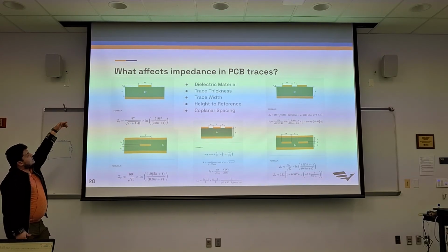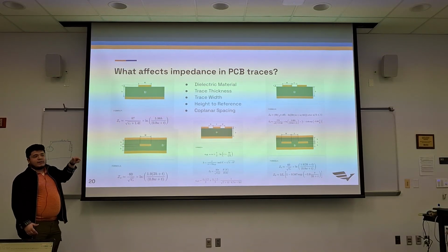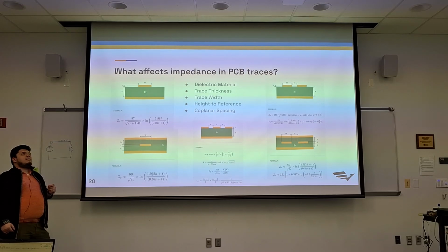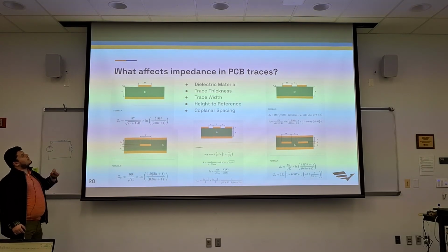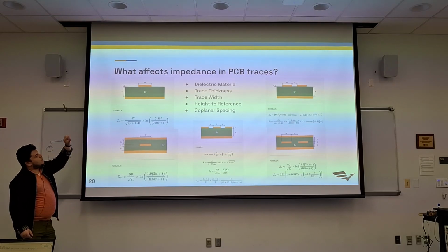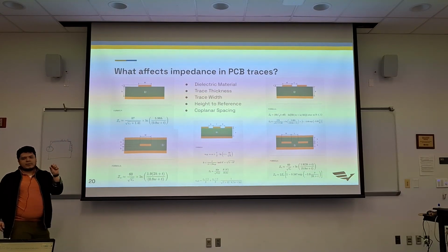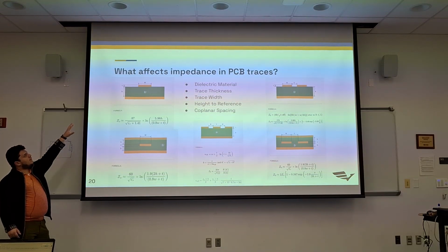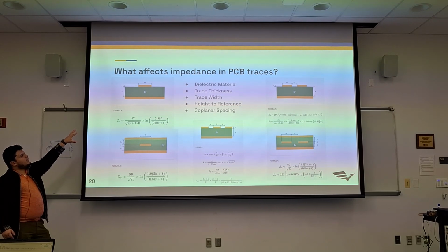So that affects it, and how far, right? So how far you are from your reference layer, and then also the thickness of the trace, like how thick is your copper. Those are primarily the things you're worried about when calculating the impedance.